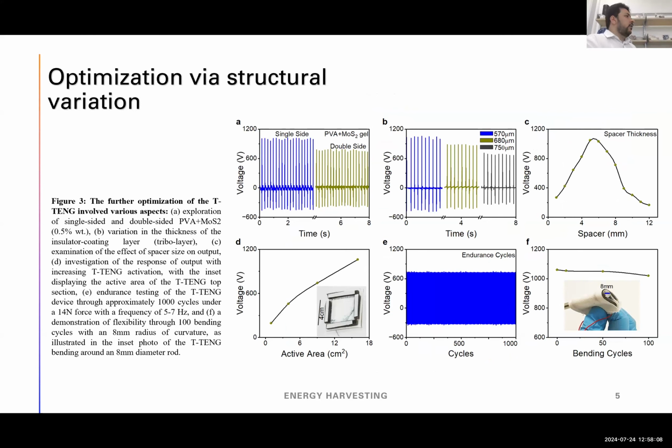And the reason is, as I already told you in the start, that for triboelectrification, you need to have dissimilar surfaces. So while using similar things on the same side, the result was reduced as compared to the single side one. Then to further optimize, I increased the passes of the insulator paste.